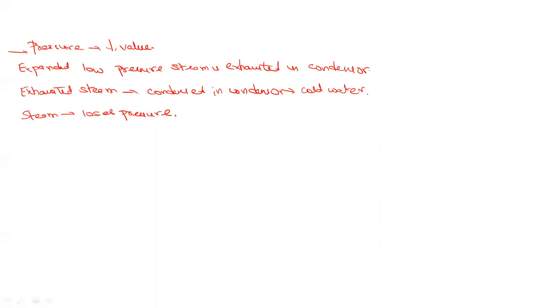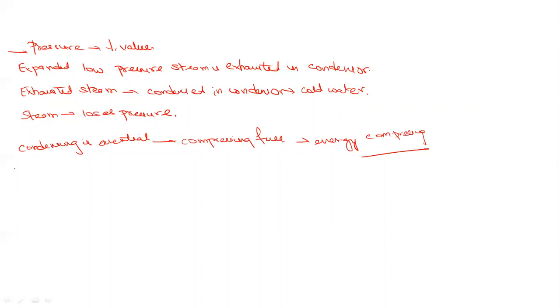Condensing is essential because compressing a fluid in the gaseous state requires a huge amount of energy compared with the energy required for compressing a liquid. Thus, condensing increases the efficiency of the cycle.